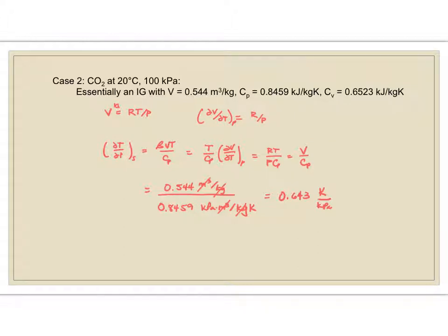And just generally, with a compressor, you never want to compress to more than 3 times the feed pressure. So let's say that I go to P2 of 3 times, so 300 kilopascals. So delta P, therefore, would be 200 kilopascals. And if that's the case, then delta T is 129 Kelvin, or 129 degrees C. Wow, I mean, that's huge, right?